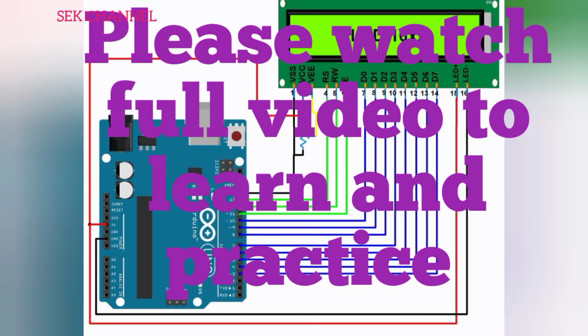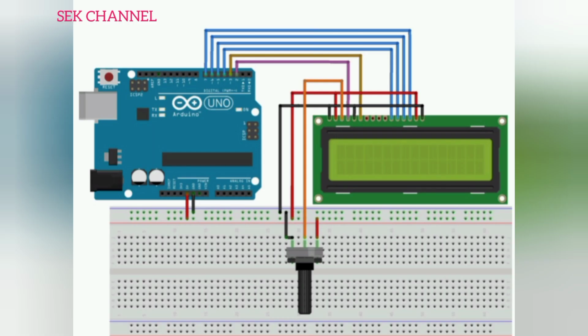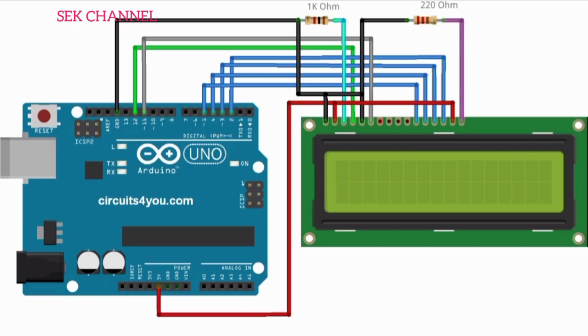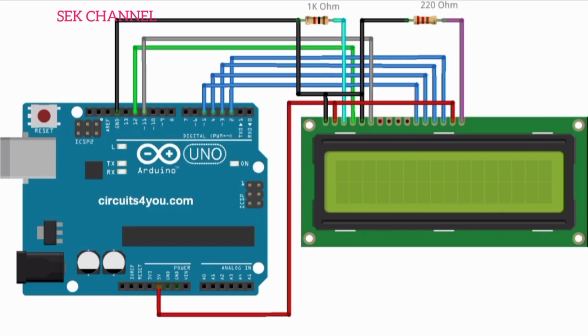In our previous video, we discussed interfacing Arduino with the LCD in parallel way at 8-bit mode and 4-bit mode. If you have ever tried to connect an LCD display with an Arduino in parallel way, it consumes a lot of pins on the Arduino even in 4-bit mode. The Arduino still requires a total of 7 connections, which is half of Arduino's available digital input or output pins.